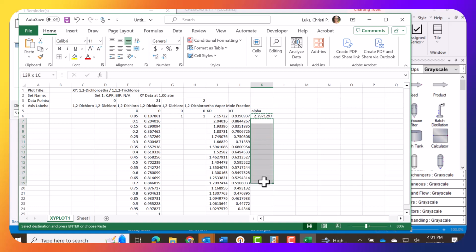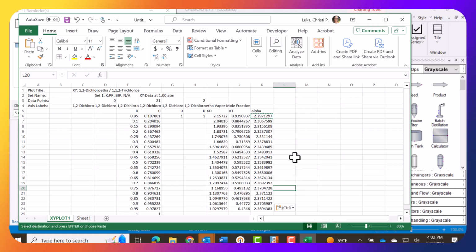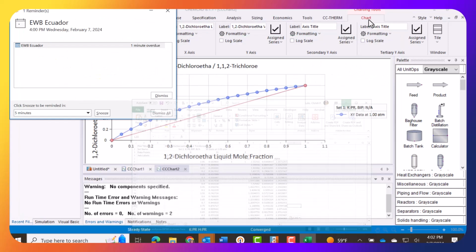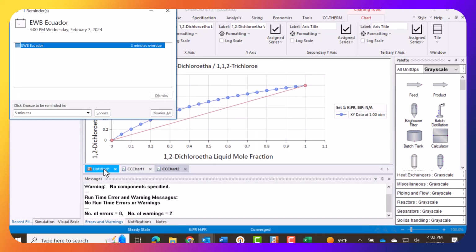And if we copy that down, okay, I did a very poor job of that. We see that the 2.24 is a little low. This is a little higher than that, but it is fairly constant. If you did the UNIFAC, what you would actually see is that it's closer to 2.4, but again, fairly constant throughout. So this isn't going to be a bad model. It's not perfect, but no model ever is. So that is a way of verifying our data.